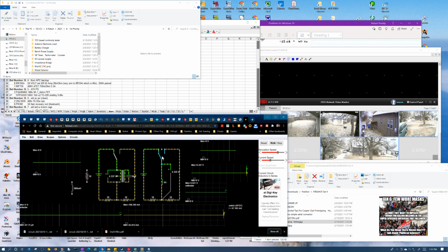Now let's give it a whack. Okay, so you can see just like before, our capacitor is hiccuping a little bit as it tries to charge up. We've got 5 volts here, 5 volts here, whatnot. And then here this is up to 8 volts, so it's a little higher. Like I said, we're about charged up. You can see we've got only about 60 millivolts across it now.